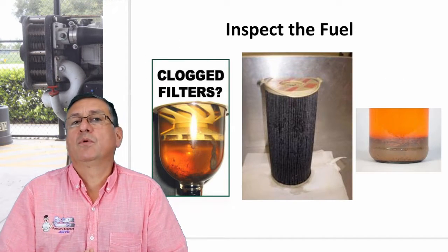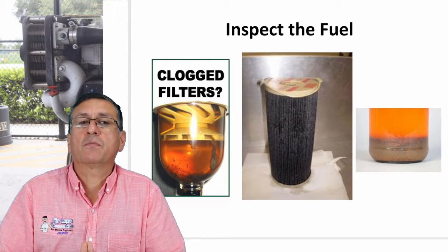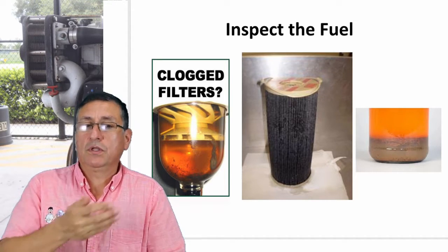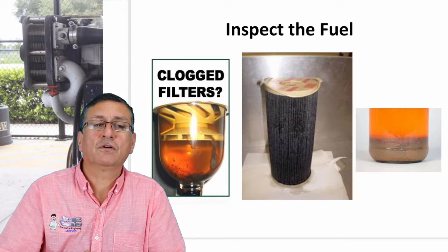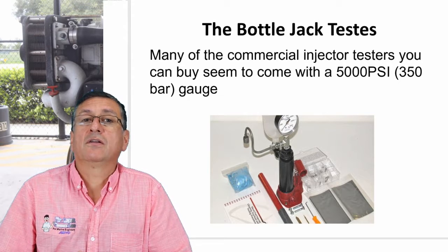Okay, my friend, be careful with the condition of the fuel. Do the service on the Racor or Parker primary filters periodically. According to the video, I explained to you step by step the procedure to do the service on the filters. The life of the engine depends on the service on the filters.